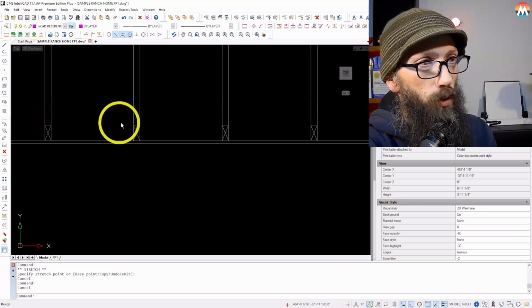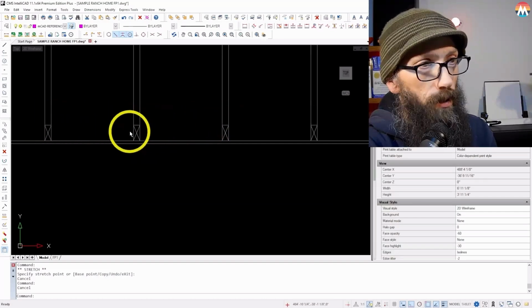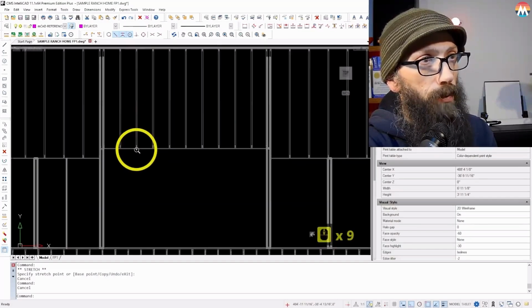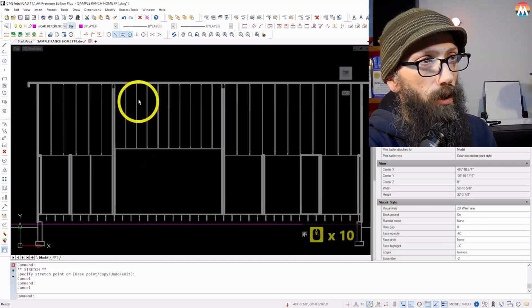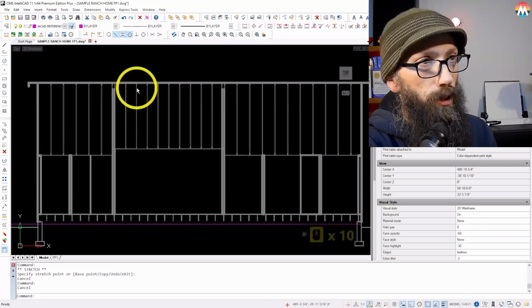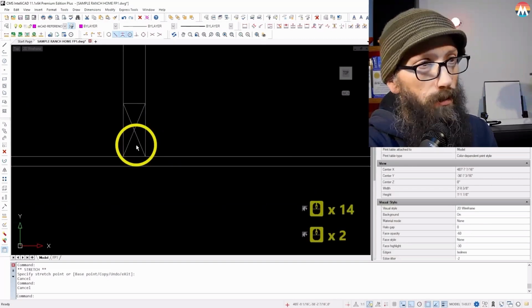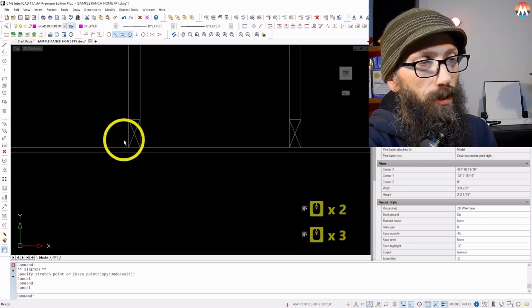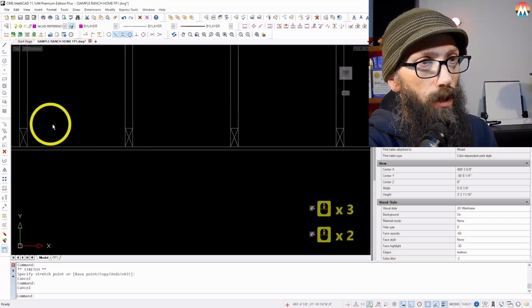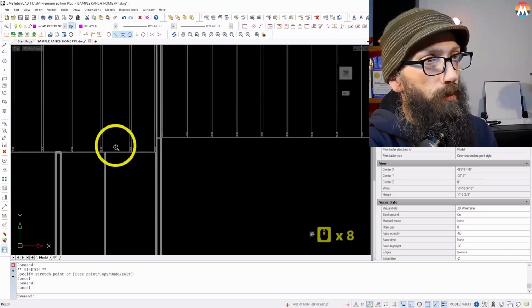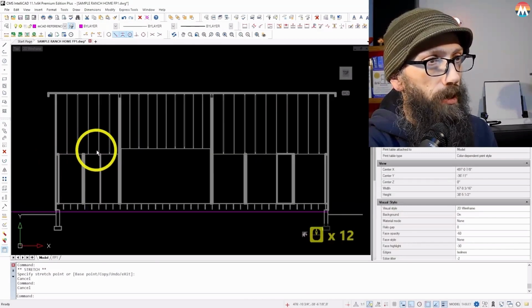But our piping is resting right on the top of this 2x4, which is a piece of this entire roof truss assembly. This is what would be called the bottom chord. And so we rest our piping along the top of the bottom chord. And we predominantly run our piping this direction.